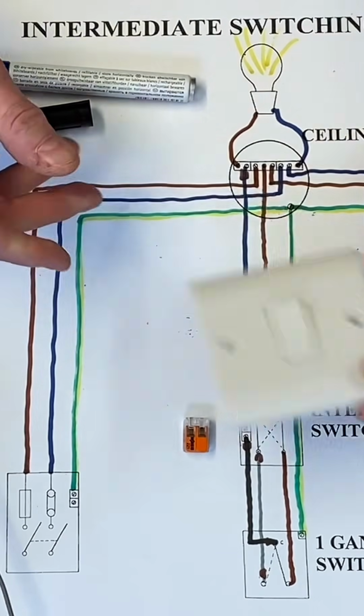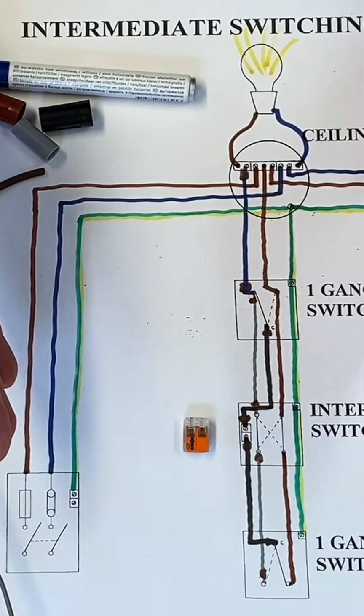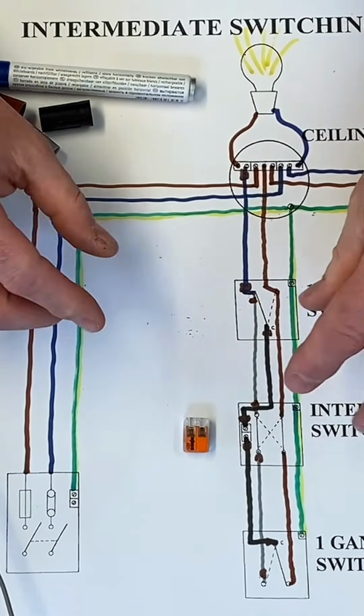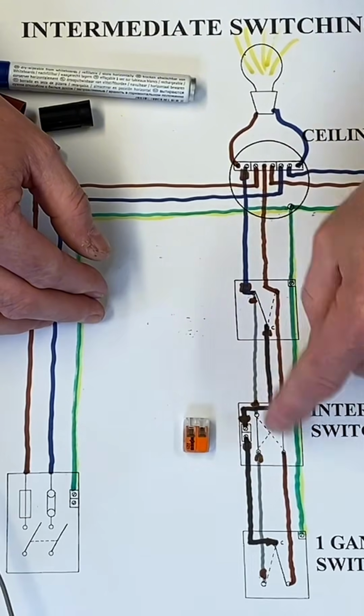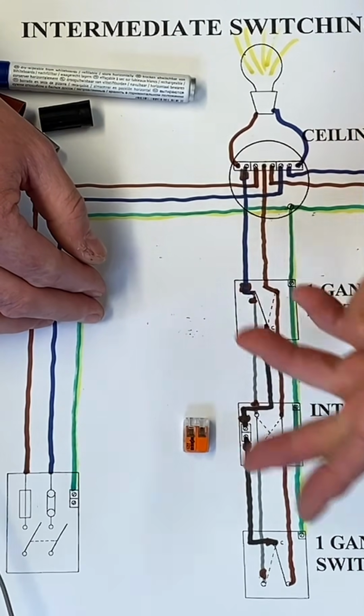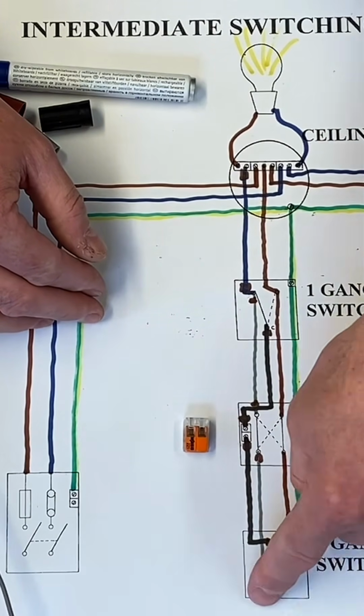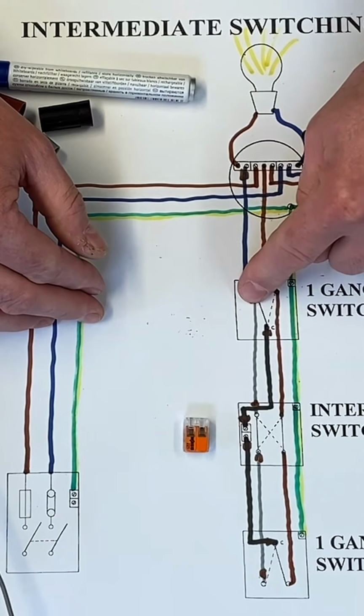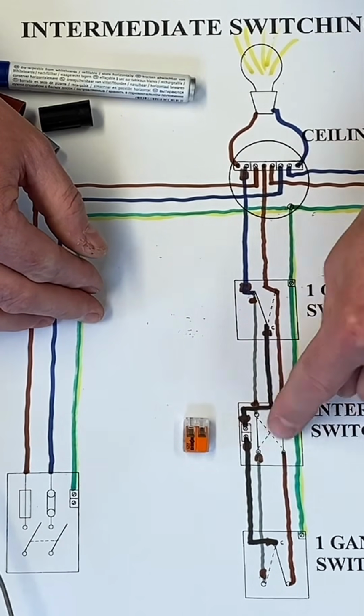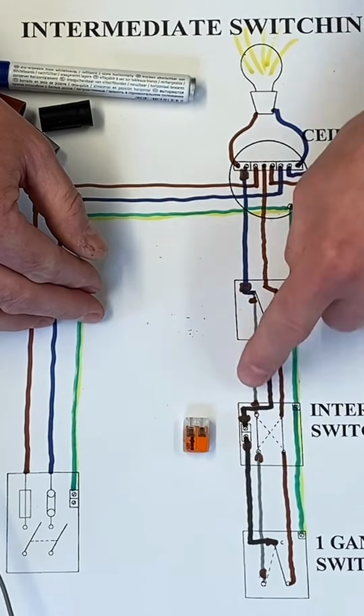That's something we'll cover when we're actually physically wired it up in the classroom or in the workshop. We'll talk about this interconnection in order to find the position whether we're on or off. You can work it through yourself, moving the blades of the switches as I did in the previous video, but just remember this one goes across both diagonals or straight through from its switching position.